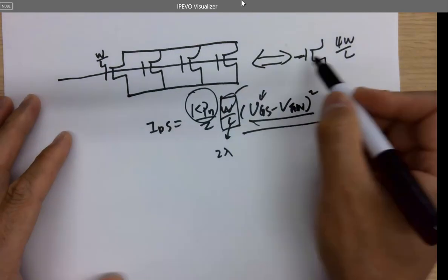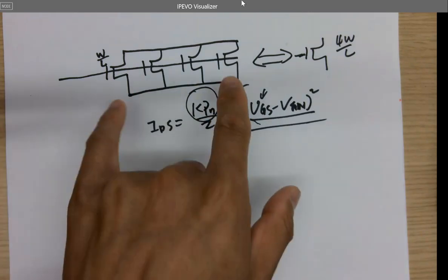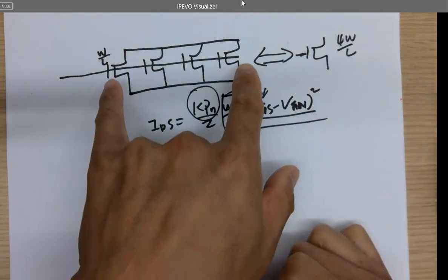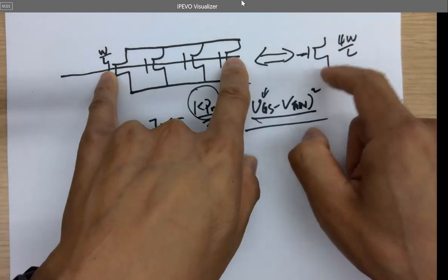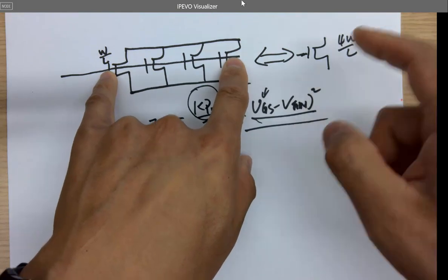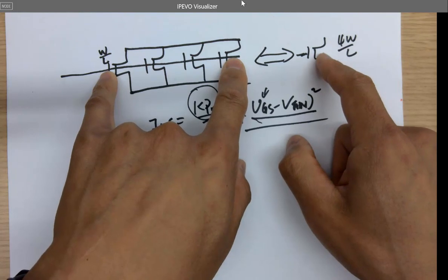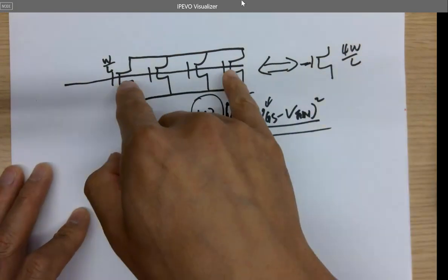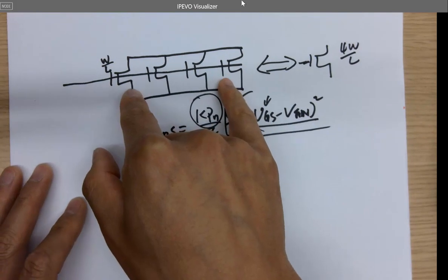So how to lay out this kind of transistor? It's very interesting. In any of the VLSI EDA tools, for example Electric VLSI or Cadence, if you lay out 4 transistors in parallel like that, you can replace them with one wider transistor, and that's still going to pass LVS or NCC in Electric VLSI. Is that interesting? It's going to work. It's considered equivalent to 4 smaller ones in parallel. So how to lay it out?